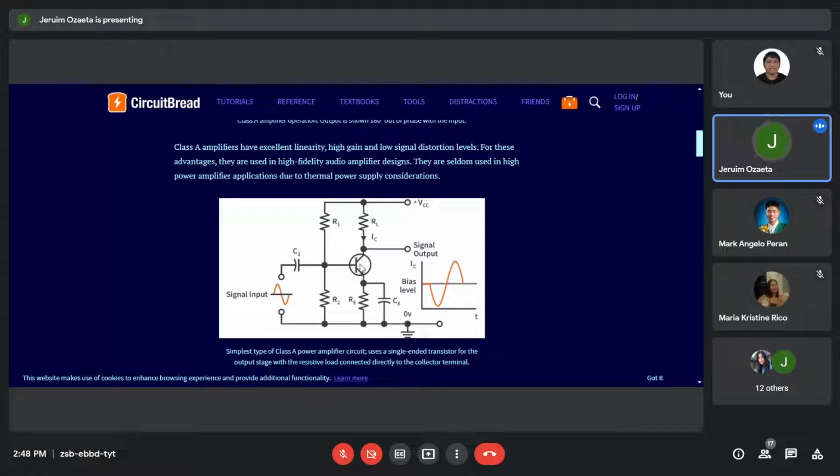When it goes up, meaning to say this becomes negative, so the transistor will start to be negative bias, meaning to say it's reverse bias. So when the transistor is reverse bias, it opens the circuit. So if the transistor opens the circuit, what will dominate will be the positive voltage present through R sub L. The positive voltage here dominates because the transistor turned off. That's why you see the signal here becoming positive. Okay? So, it became inverse because of this.